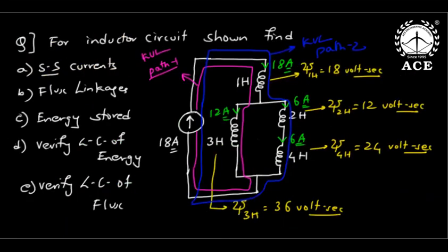I will give an example. Suppose you imagine, in capacitors also the same concept will come, and in inductors also a similar concept. I will argue like this. In two series inductors, what is equal? Current is equal. But fluxes will divide. Okay, fluxes will divide.